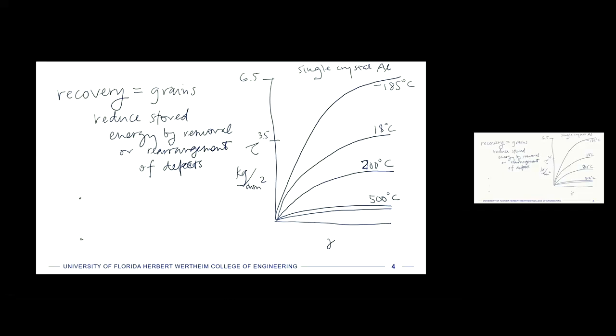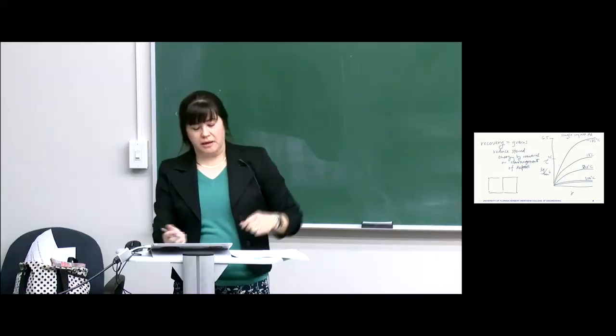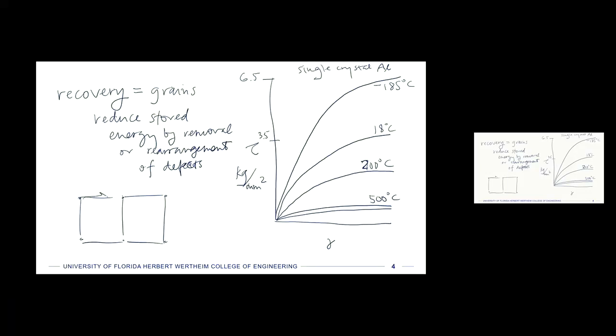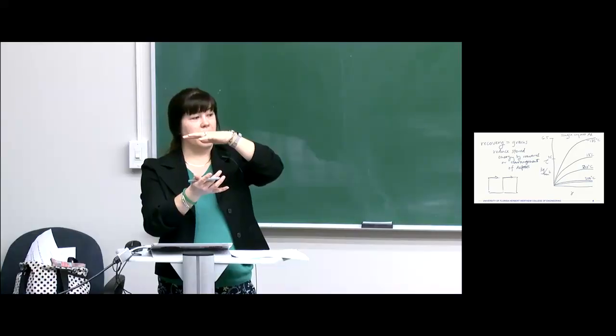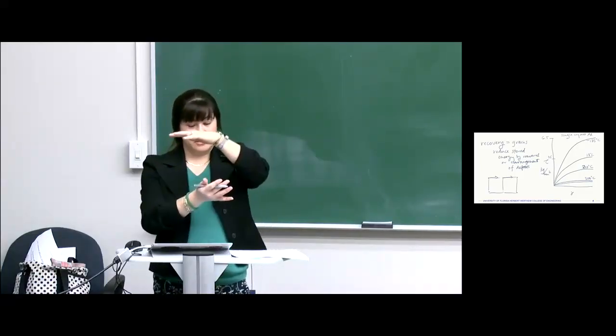Like I'm just going to draw it real quick again here, like this. All right, so we have like a crystalline structure, right? And then we start to apply some kind of shear strain, right? And we move those atoms over such that they slip to the next spot, right? And minimize their energy again.